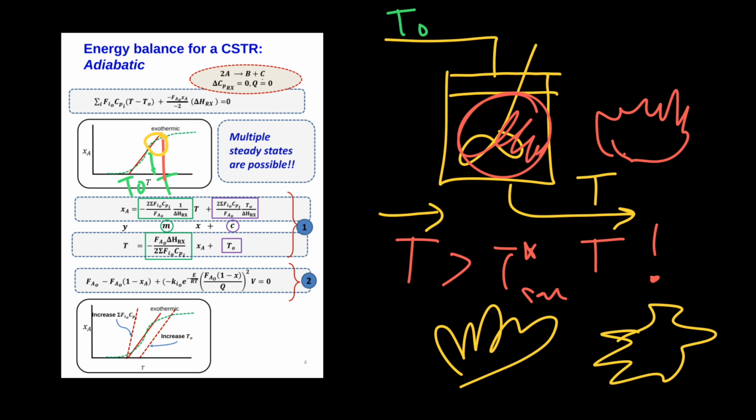So, a word of warning: when you solve for exothermic CSTR reactors, please consider the graphical approach so that you don't just fsolve and say, yeah, I'm going to get a nice 90% conversion in this specific reactor. Evaluate whether other steady state possibilities do exist. Not only this way, but the most convenient way of visualizing this is to construct the two equations that you must solve simultaneously on a single axis set.